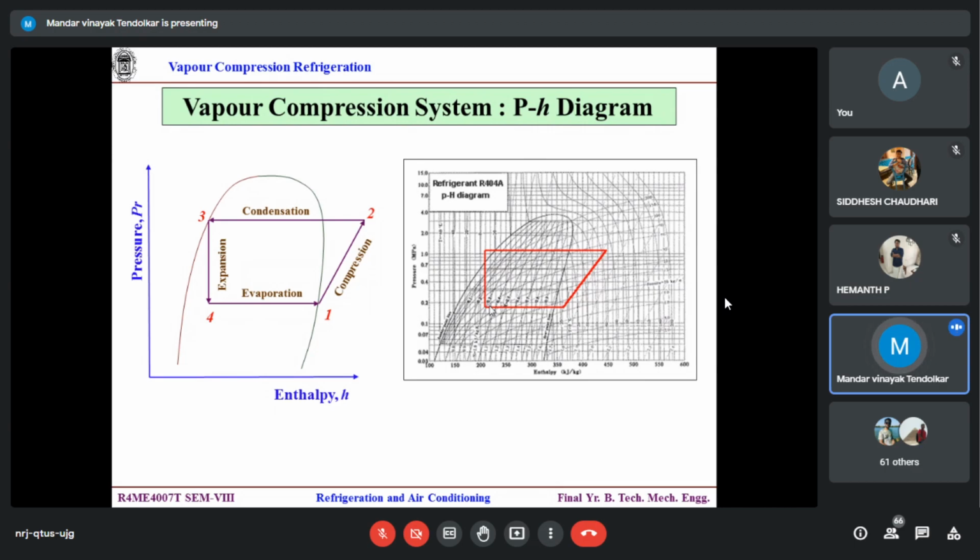The compressor part is simple. It is gas. But the expansion part is very difficult. It is liquid plus vapor. Initially, the start itself is liquid. At the end, liquid plus vapor. So it is always a theoretical assumption that the process is an isenthalpic expansion. The closer you try to attach to this theoretical assumption that the enthalpy remains constant, the better is your performance. There is absolutely no practical guarantee that the enthalpy would be constant.